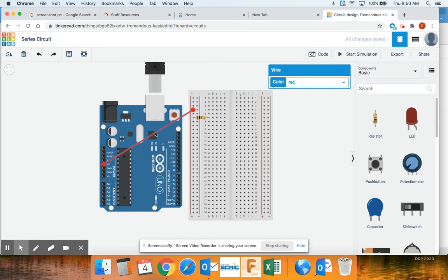So it's going to jump 5 volts into the positive. All the positive terminals are connected, so it's going to jump through the resistor. From there, I'm going to bring in a push button switch. Push button switch only works in a very particular way. So in this case, I'm going to have power through the resistor to terminal 1A to terminal 1B, and then it's internally jumping over here and then coming back this way. So then I'm going to have a lead out of there, and I'll make this red again.